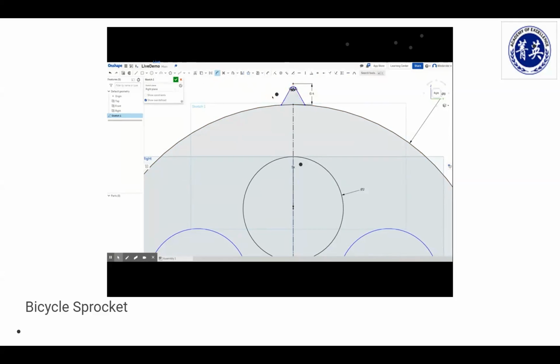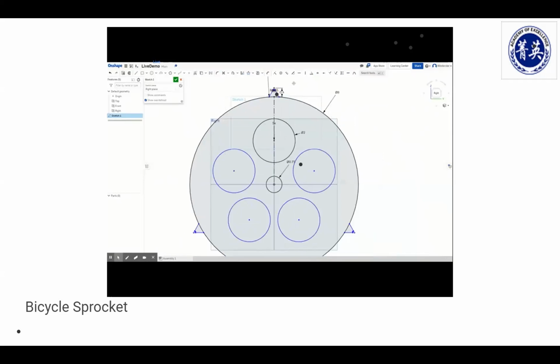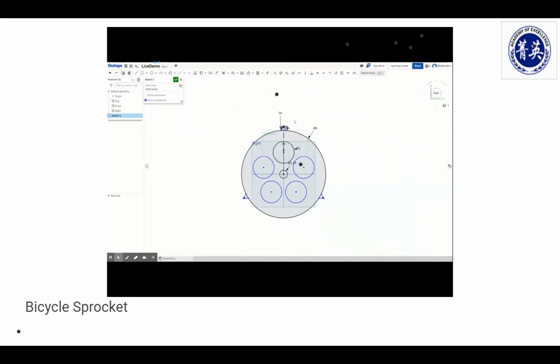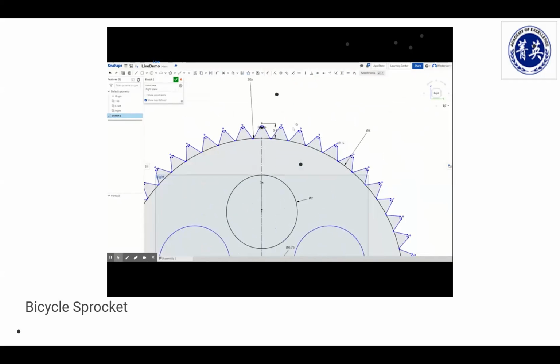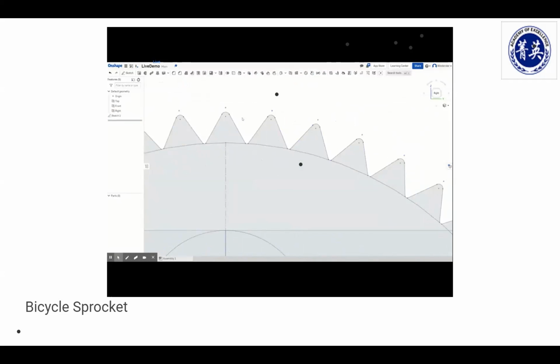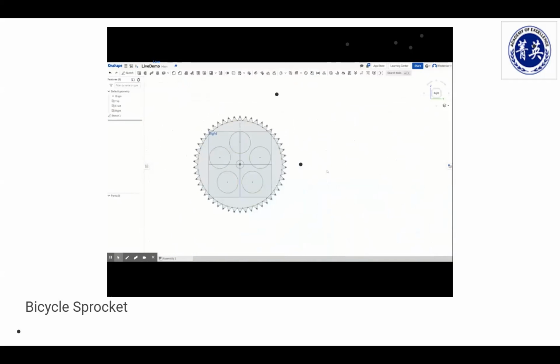0.05 degrees. Here we go. So now let's repeat this pattern around the bigger circle so we can generate enough around the whole wheel. So how many of those do we need? Let's say right now the customized standard version is 3, as you can see. Let's make it 50. One thing to look out for is to make sure these triangle lines do not crisscross each other. So now the 2D rendering is complete.